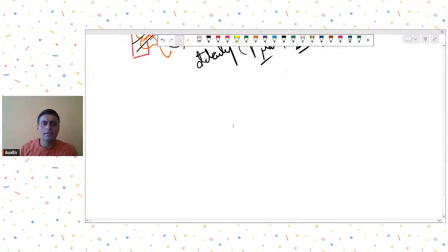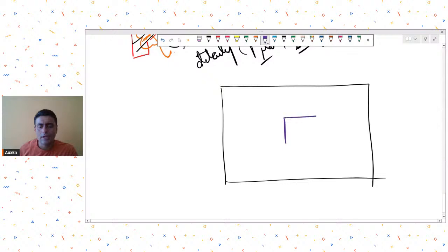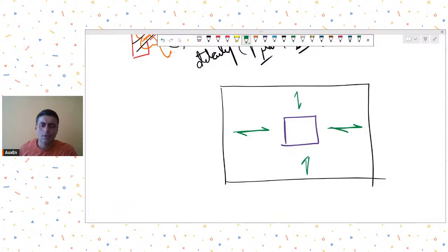So the best practices when you have a slab cutout are that wherever there is a slab cutout, especially if that cutout is large, you need to see if the load path is getting disrupted or not.